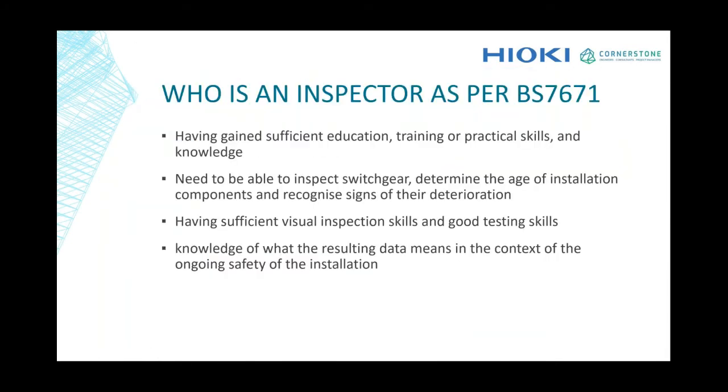Who is an inspector? Actually, the person having good education and training or practical skills knowledge, and he will be able to inspect switchgear and determine the age of installation components and recognize the signs of deterioration also. And he must have sufficient visual inspection skills and good testing skills also, and the knowledge of what the result data means in the concept of ongoing safety of the installation also.